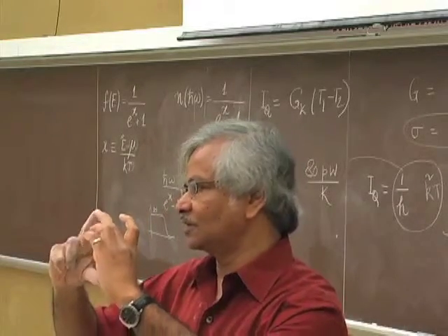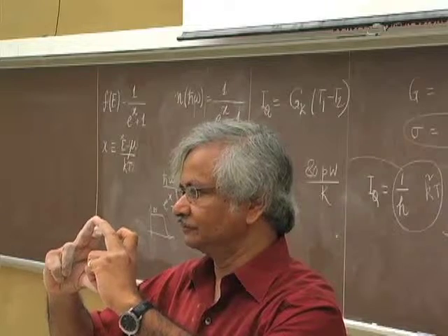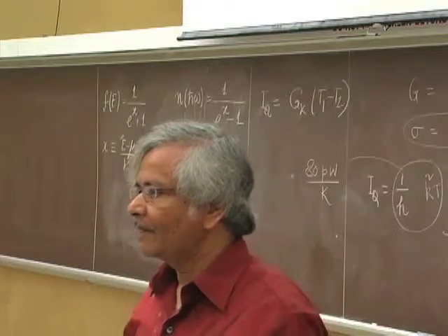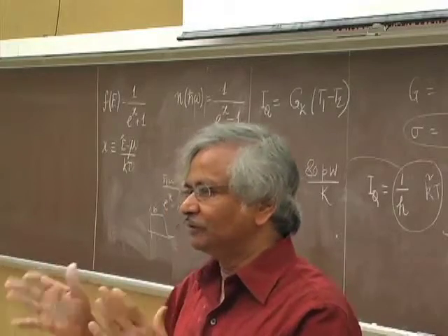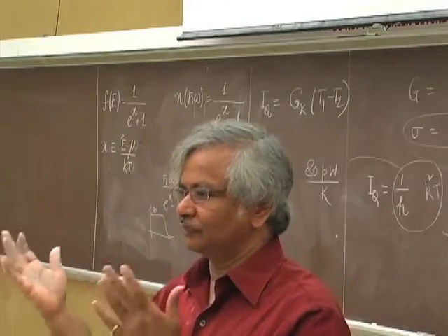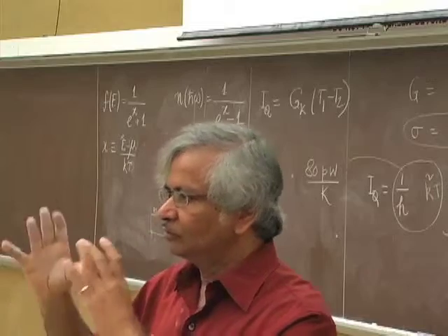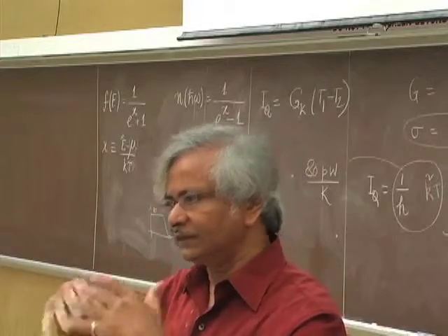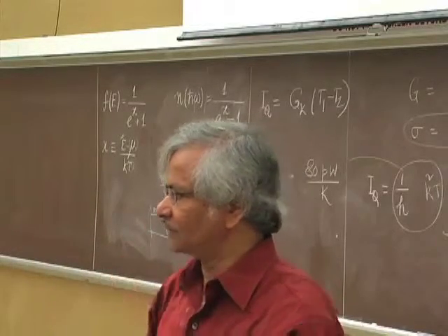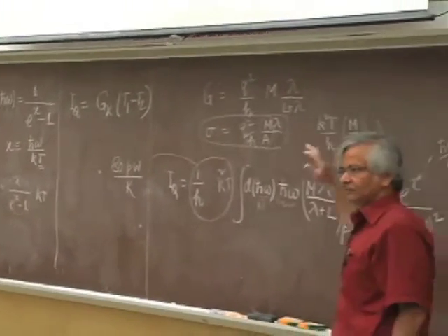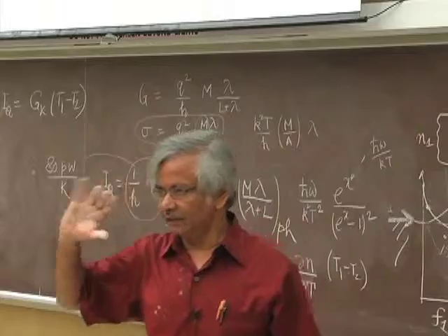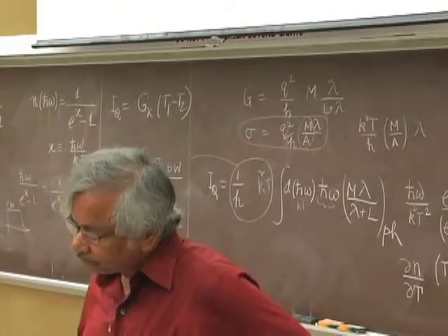Well, it's almost like asking how many atoms you have in a cross section. Whereas in semiconductors, the de Broglie wavelength is more like tens of nanometers, and so the number of modes is a whole lot less. And that's why semiconductors conduct a whole lot less, because if anything, semiconductors have much better mean free paths. So it is really the M that cuts it down so much.